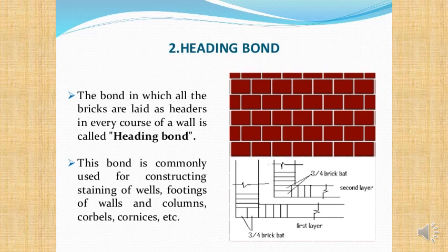And by doing this, you get a bond which is quite a bit stronger. It's actually slightly stronger than the stretcher bond, believe it or not. But the real advantage with a header bond is because you have more length going into the wall, you can actually narrow it down a little bit.